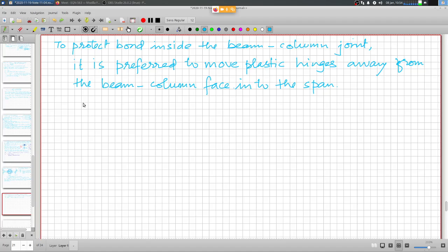But you should also remember that this beam column joint that we have discussed, the same behavior happens for steel structures also, and it is more vulnerable there because the panel zone is only a very flimsy web, right? So you need to provide for web reinforcement or web stiffening in order to increase its capacity so that it doesn't fail.